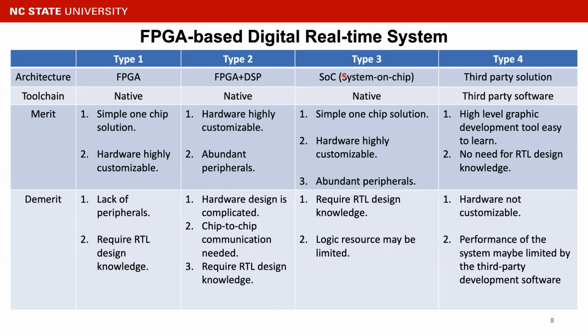Thirdly, we have the system-on-chip architecture, which provides a simple one-chip solution with highly customizable hardware. Also, it can include abundant peripherals. This platform also requires register transfer level design knowledge, and the logic resources on chip may be limited when compared with the first two architectures.